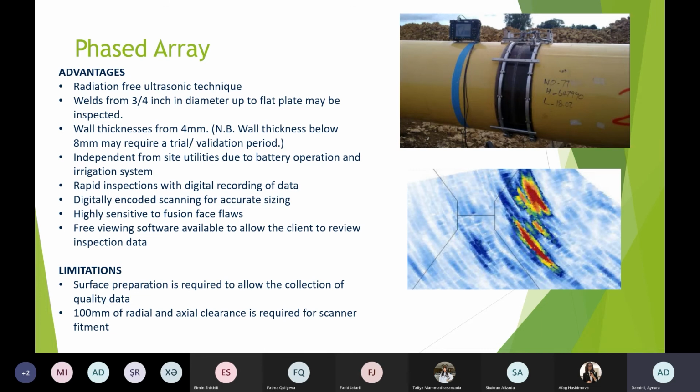on an insulated system. We need to remove insulation, and to remove insulation we need to know operating parameters. Insulation is applied on site, in normal cases, for personal protection, because it's a hot system and anyone can go near, touch it and burn themselves.